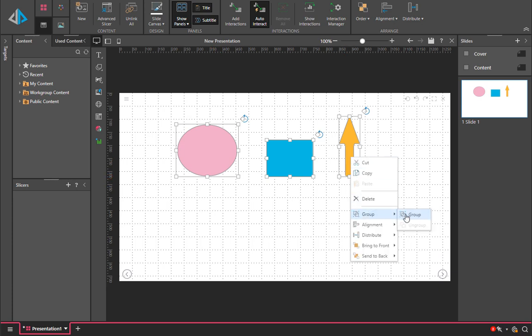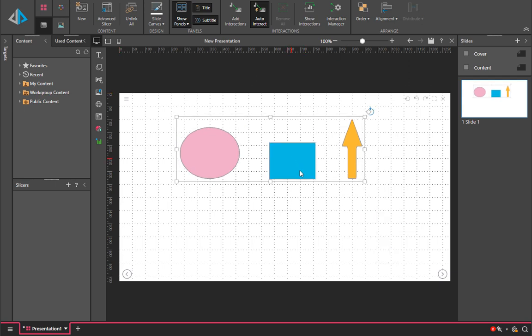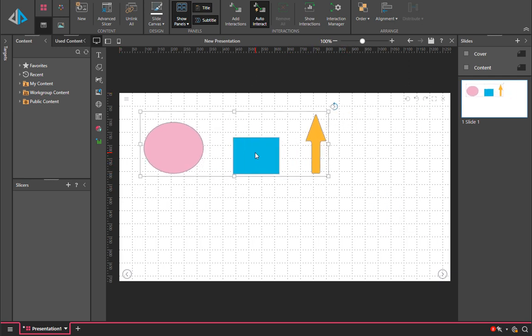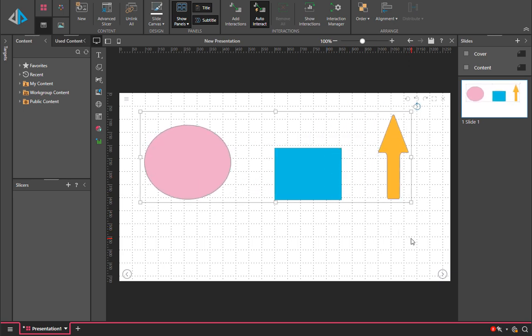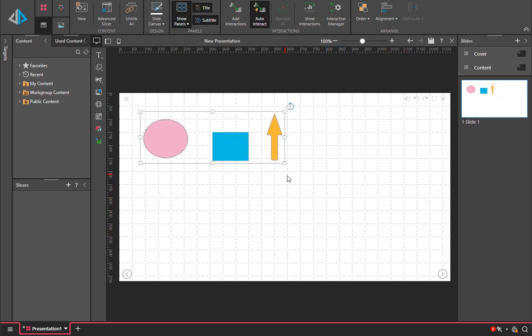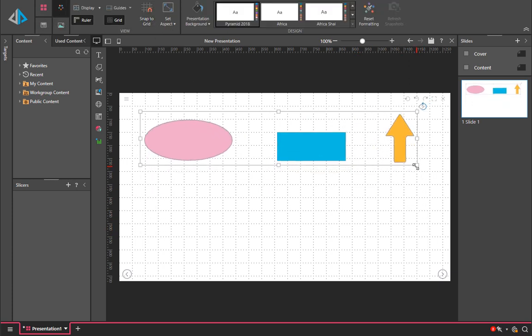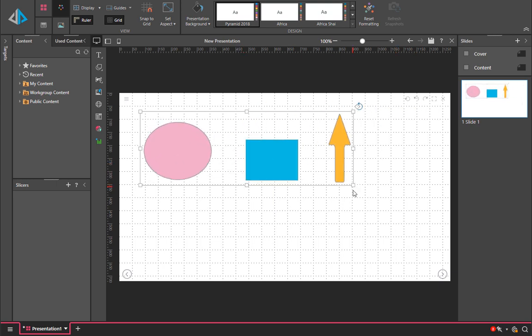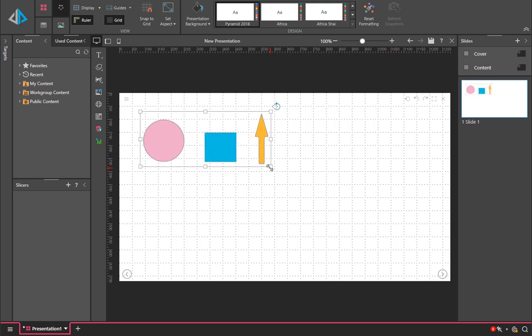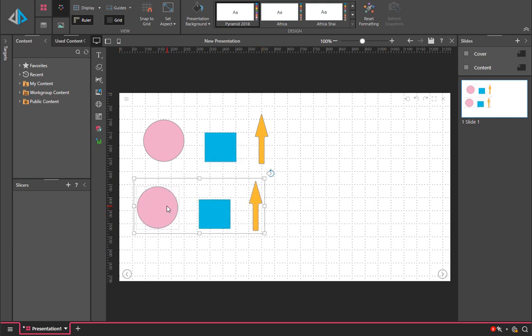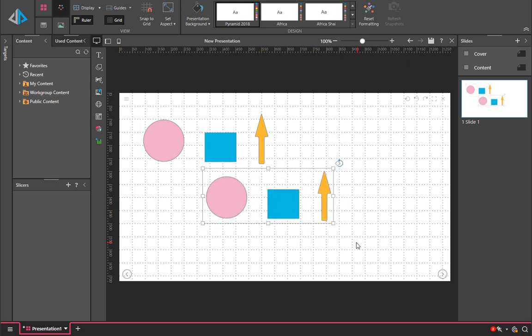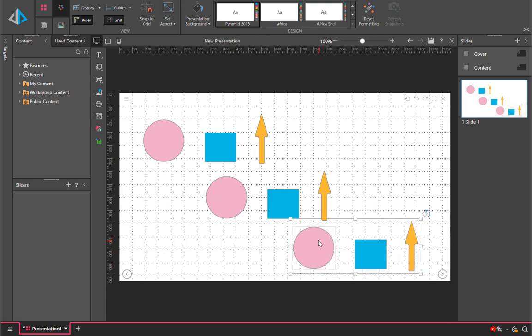Grouping is a very useful feature because it creates a single entity out of all the multiple child entities. This gives us capabilities including copy-paste, stretching and growing, and a variety of other tools. Grouped elements will shrink and grow in proportion to their size and also to their spacing. Conveniently, a grouped element can be easily copied and pasted, and the entire group will be pasted and duplicated accordingly.